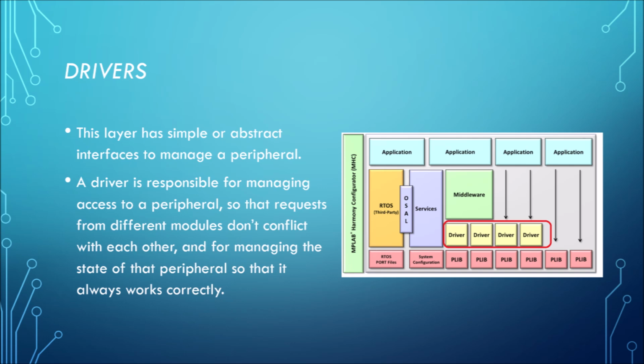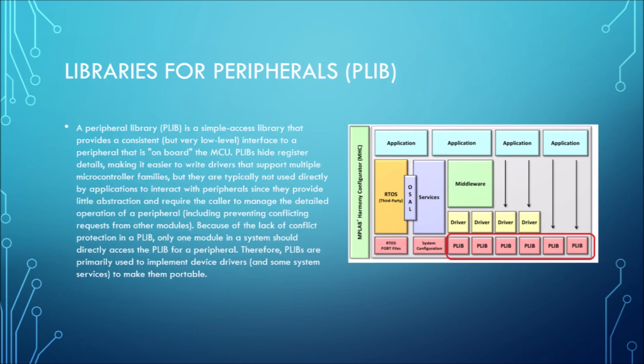Each driver can have multiple instances, allowing to manage several peripherals or modules of the same type in a project. Configuration includes common parameters between instances, along with specific options for each one, depending on the requirements of the peripheral or application. Peripheral libraries, as their name indicates, allow you to configure the characteristics of peripherals. For example, in a UART module, you configure its speed, the number of bits, parity, interruptions, etc.